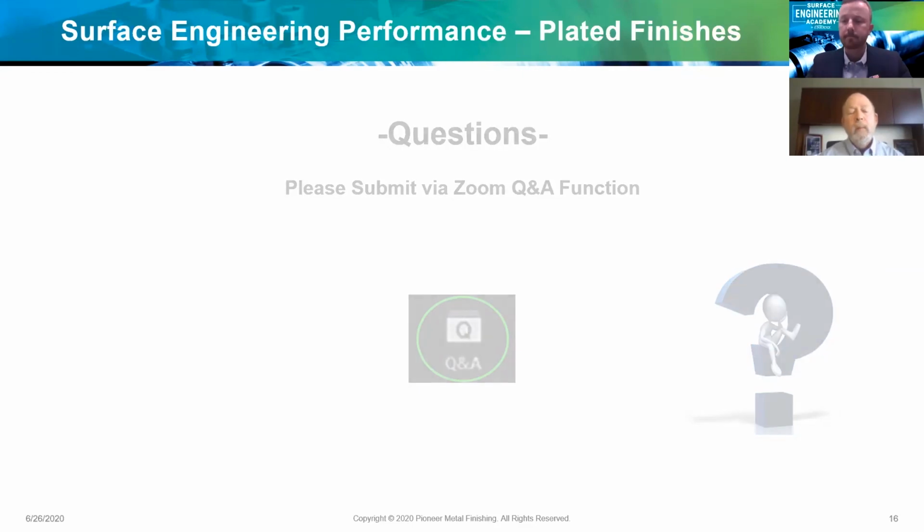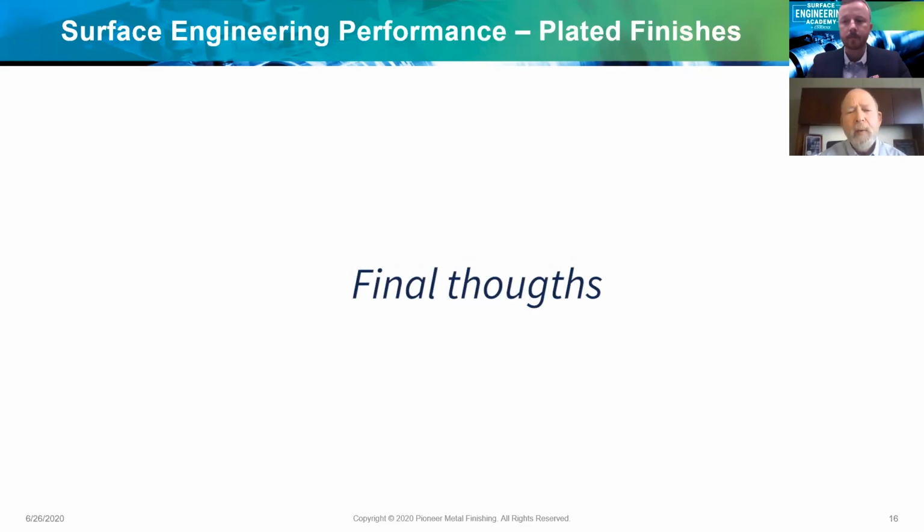I guess just overall, when you're going to get involved in a project, it is critical to understand why you would be doing plating processes and get your plater involved early on in the process, especially if you've got some ability to choose the plating type and the different attributes of the plating type, thickness, and so forth, the base metal that's going to be chosen, things that are important to the plater to make sure they can be successful for you.